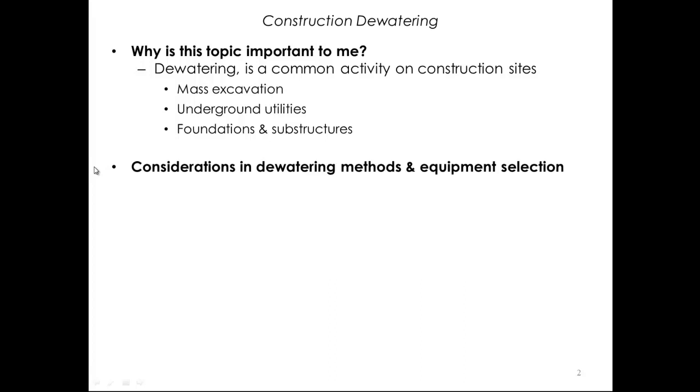Construction managers must consider a number of factors when planning dewatering operations. For example, will the soil give up the water? Not all soils can be dewatered. Granular soils are fairly easy to dewater, but other types of soils may not dewater at all, and the excavation work may then require the use of watertight sheet piling systems.